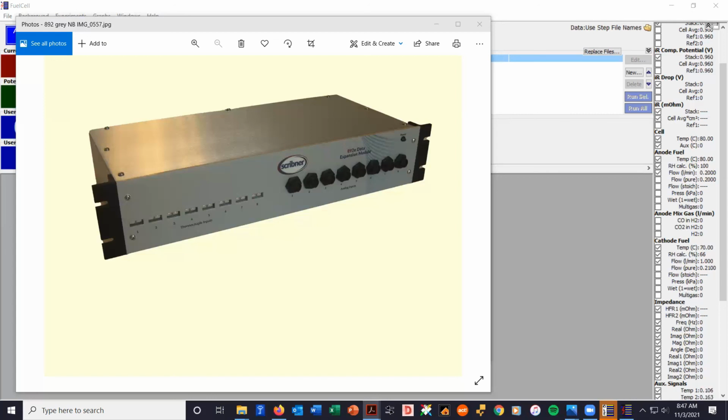You'd want to think about the possibilities, and that's a very good question. You typically would want some kind of check valve to prevent backflow. You want to avoid the possibility that the corrosive gas could flow back up into the test system via the line. So you would use a check valve, and that also has to be part of the user's plumbing.